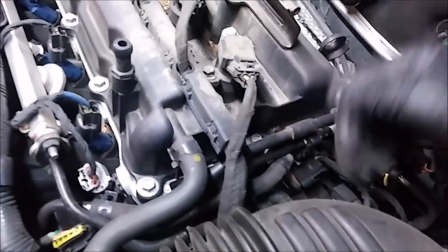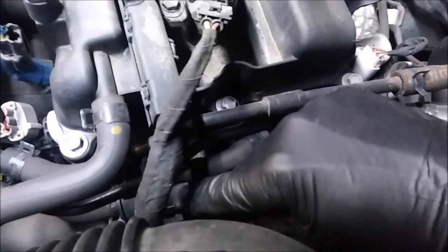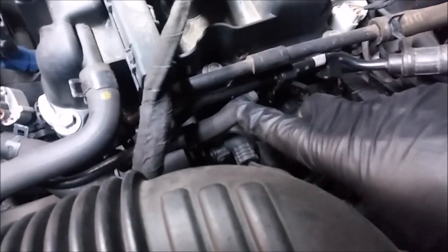Alright, so this is the vehicle, guys. What I'm really looking for is the purge solenoid, and I found it. It's on the driver's side of the valve cover, and it's this electrical connector right here. It's kind of tucked away. This electrical connector comes in, and this unit right here that I'm pointing to is the purge solenoid. It has a vacuum line coming off of it right here, and this vacuum line goes into a metal pipe here and connects to this hose that I'm shaking.